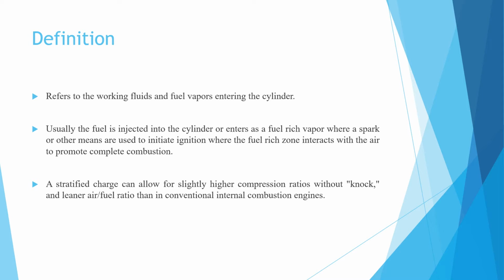It is an engine which is midway between the homogeneous and the heterogeneous charge. Homogeneous charge basically means the SI or spark ignition engine, and heterogeneous charge means CI or compression ignition engine. The charge stratification means providing different fuel air mixture strength at various places in the combustion chamber.